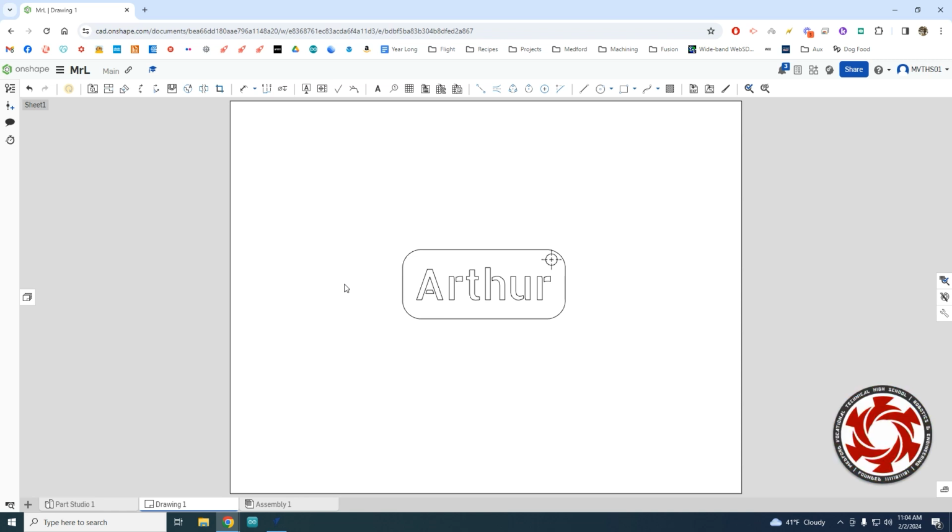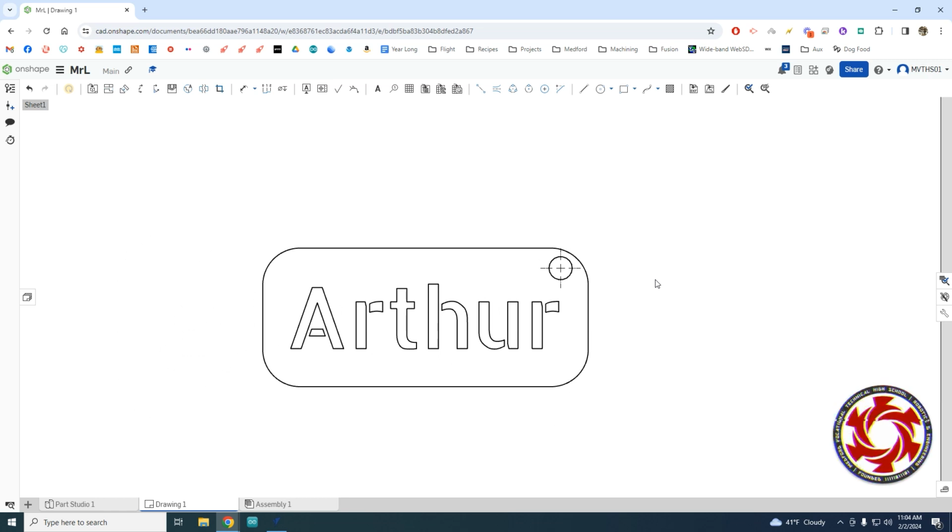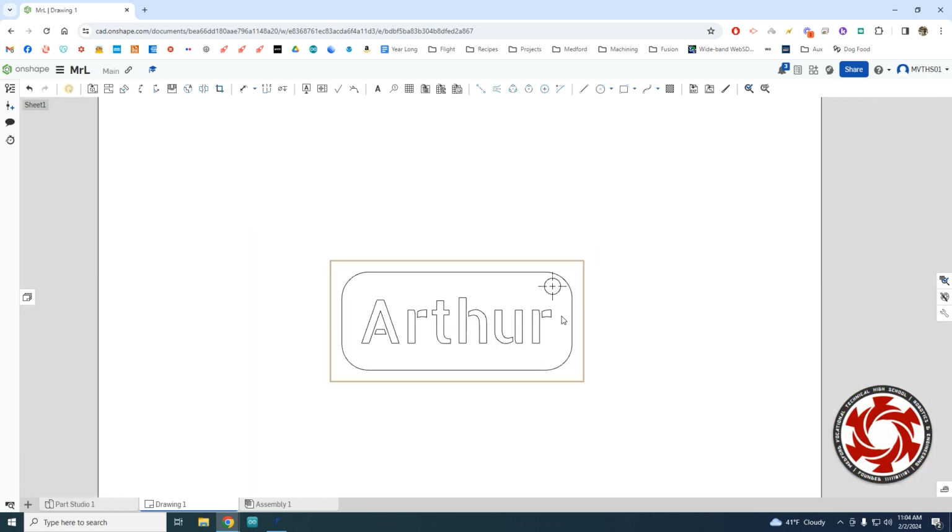The last thing, or second to last thing really, we need to do is you'll notice this circle has these crosshairs in it. We have to get rid of those for our laser cutting. This is a default process that OnShape does, so there's no other way to get rid of it except what we're about to do. So hover over your drawing, right click, and you'll see this show hide at the top. Come on over and go all the way down to hide auto center marks and click on that. That should delete those center marks in the circle, and now the drawing is completely ready to export for laser cutting.